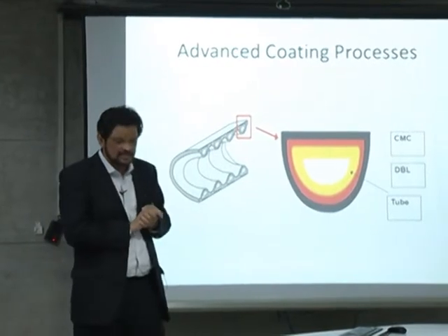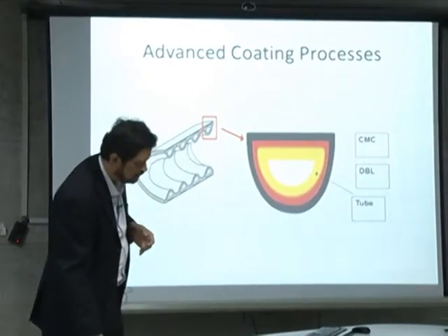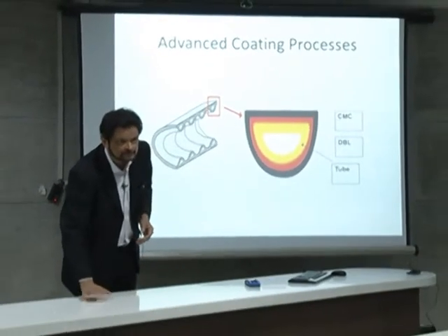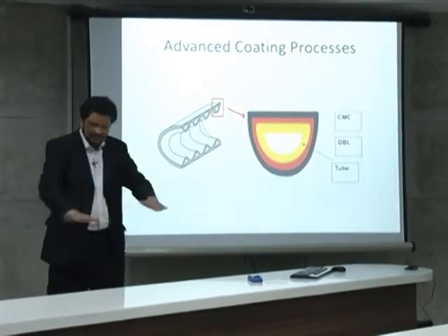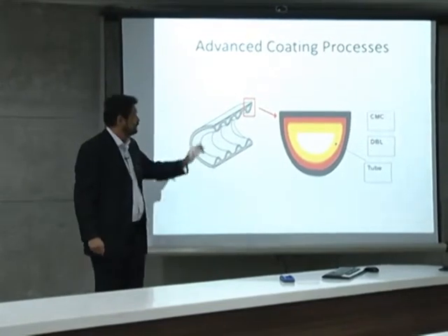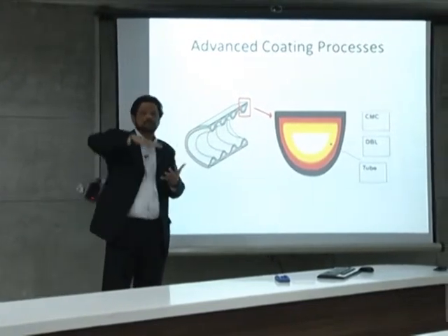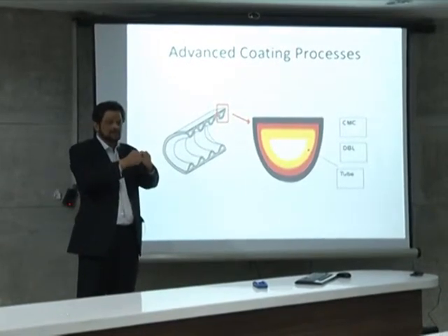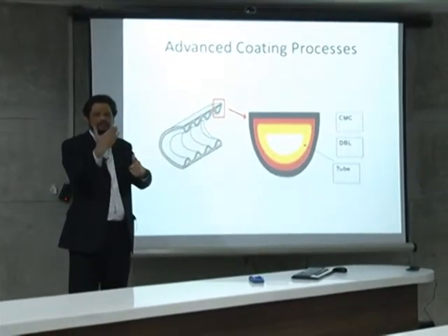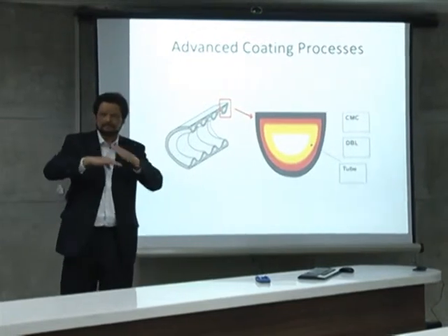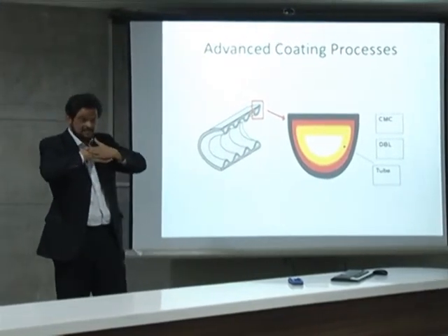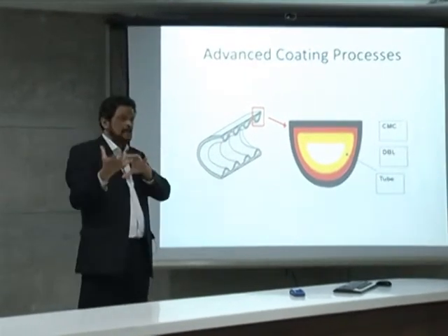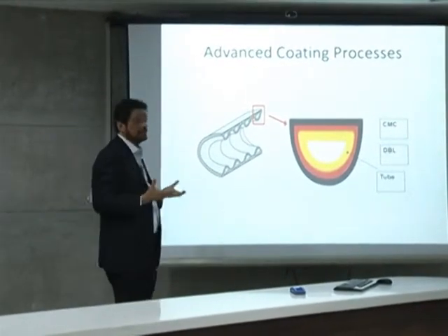Problem with coating is that if you look at the coating, now this one probably has some kind of a laminate on the top, right? This table, it's a coating. But when you look at this type of application where the temperature goes up and down, you can imagine it will change the shape slightly and the coating will flake out. It will get released because of the stresses when it expands and contracts. So how do you take care of that problem?